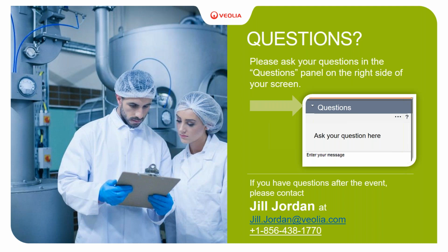I always tell the story of a plant at a pulp and paper mill we did years ago in Canada, where we did a year's worth of pilot studies and fed micronutrients all the time. To make a long story short, about 6 to 9 months after they started up, the process started to go bad. They had me come up. And what finally turned out to be is that they had stopped adding micronutrients because the pump had failed, and because they were adding so little, it obviously didn't matter to them.